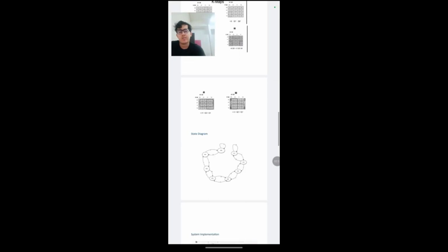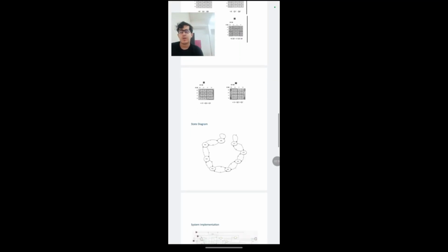And what is the state diagram, and what does it help us with? It helps us see the direction of x, which is just our direction for the elevator, while using our model, which is the 3-bit system. So it's a transition through states from 000, the three zeros at the beginning, to 111, and the control counts upward to track the ascending floor.